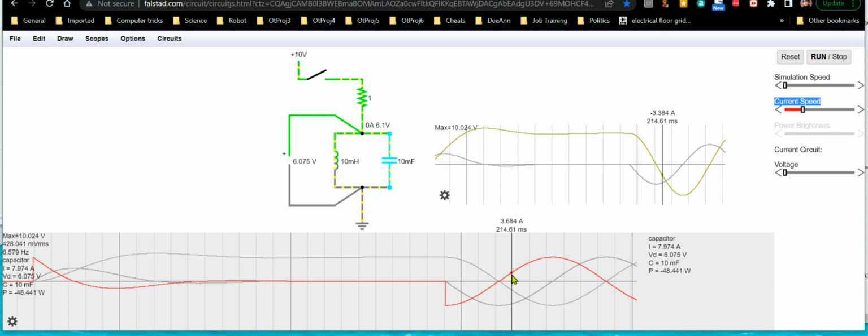But now right down here, the case is flipped, which means the current's flowing in the opposite direction from what you see here. So the current's flowing from the inductor into the capacitor, from here to here. Basically the inductor is charging up in reverse polarity.